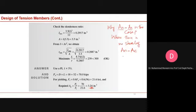Otherwise, if you have a shear lag, then effective area is not equal to net area. Effective area is equal to net area multiplied by this relationship. This means that you have to calculate the U value, and the U value you can calculate by this relationship.